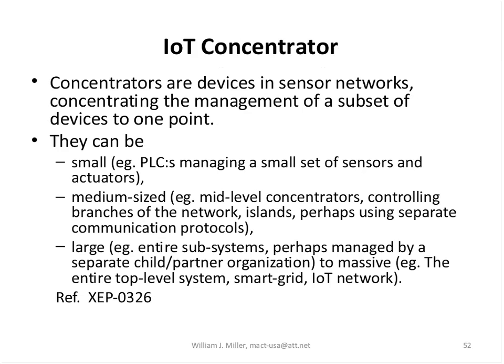But then addressing large scale systems, again, that's another important element, where you see it in things like smart grid and Internet of Things, where we need that scale to address. Concentrators can do that. And by the way, concentrators are the way that we are addressing translation of legacy device protocols, where by writing the code to translate from something like 61850, which I'll talk about a little further later, you'll be able to transport that via XMPP.